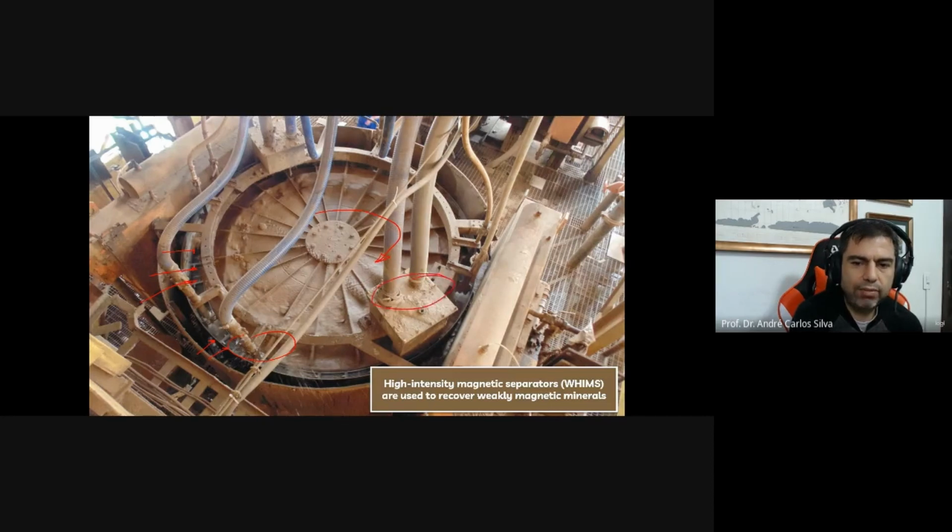So in here, I'm feeding the machine. Okay, that's the pole. The pole is going to be right here. And as you can see, I have, for example, a north pole in here and a south pole in here. So this machine operates with just 2 poles, but I could easily adapt another pole in here and another pole in here, and then I have a 4-pole machine.